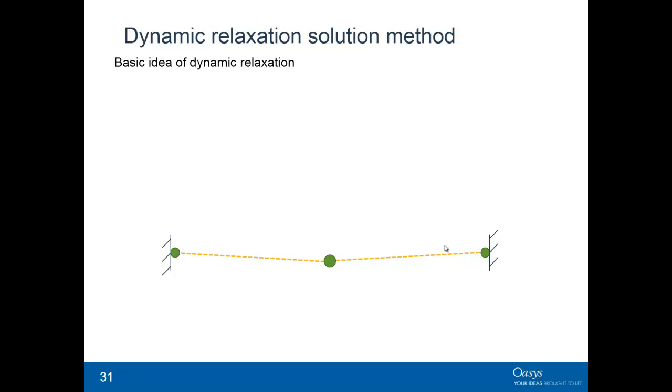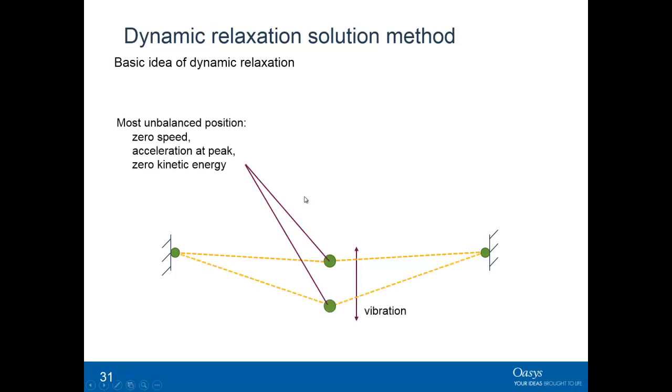The way it works is that the structure is basically thought to be bouncing around. The stiffnesses are replaced by masses, connected by stiff elements, and as the structure moves, you have these sort of extreme points where the speeds reach 0, but the accelerations are maximum on them.